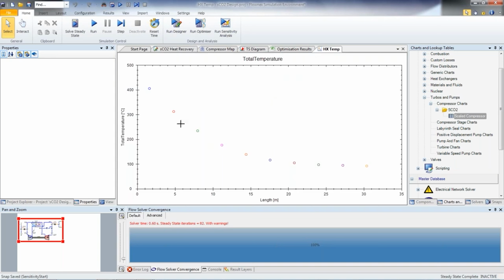So we're able to view the temperature of each of the increments, but we can quite easily change this to another property. So for example, in a heat exchanger where you're looking to model two-phase boiling, you could visualize your two-phase convection coefficient and just do a sanity check on your model and make sure that your two-phase convection coefficient is increasing and decreasing as you would expect in the boiling regime.